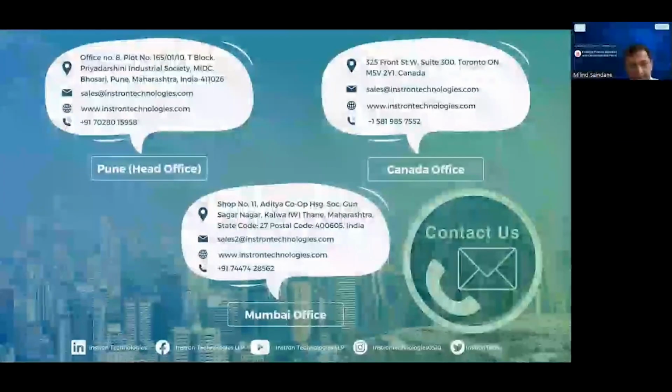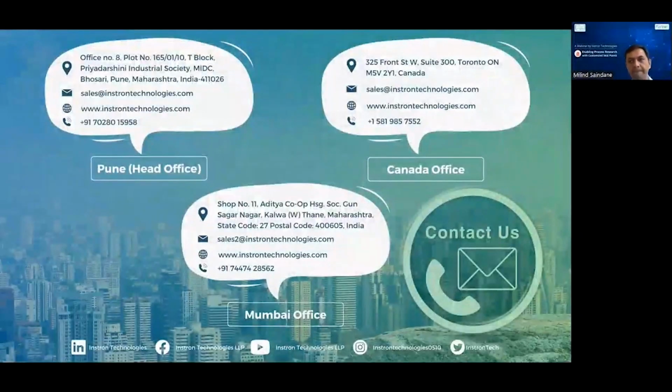Yes. We have delivered one reactor for the naphtha reformer, and the reactor temperature was 900 degrees Celsius. As you know, SS316, or stainless steel, can't handle temperatures of more than 600 degrees Celsius. The material of construction of the reactor was Incoloy, and the reactor was designed using the API code. I hope that is the maximum temperature we have handled.